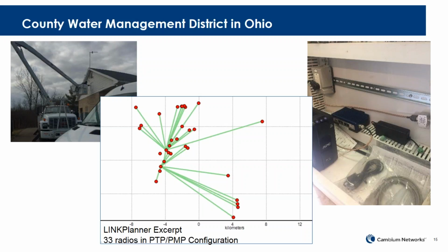At each one of those red dots, you'll see in the upper left there's a building with a post sticking out the top. That's a Yagi antenna, and it's pointing back to a hub. Inside that building, there's a little cabinet, and you can see on the right that blue radio sitting on the shelf, one of Cambium's radios. That radio is going to connect to sensors and pass that data over the green bars back to the hub, and then take action back at the SCADA master.